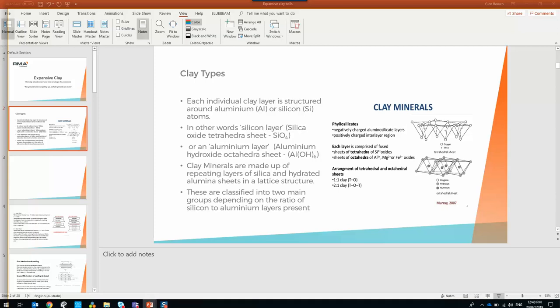Basically what you're trying to do, but also when you do that, you've got to make sure before you place any fill, your natural soil should be shaped and free draining, because I've seen houses in Goondiwindi where, on a sloping site towards the river, they build up a big fill platform and the water just ponds up against the fill. It's like a time bomb, it just takes 5 or 10 years to eventually seep under the house, and they wonder why it's popped up. So it's important to get that right, and we actually did cross sections of the natural material and told them they had to get that signed off before they place the fill.